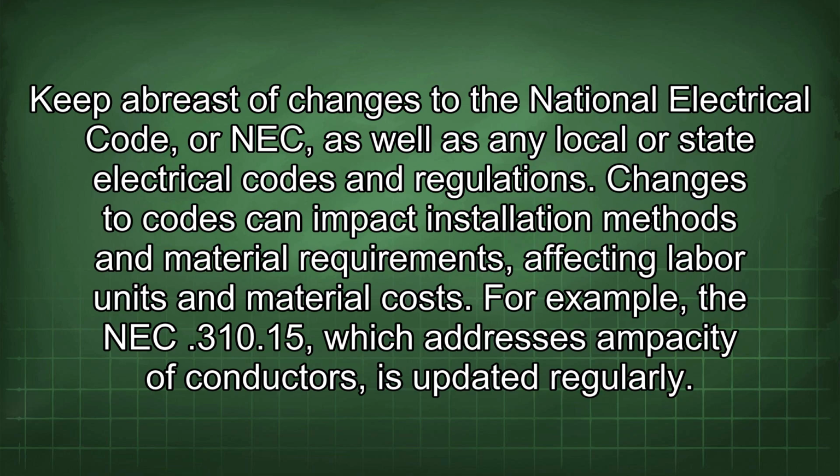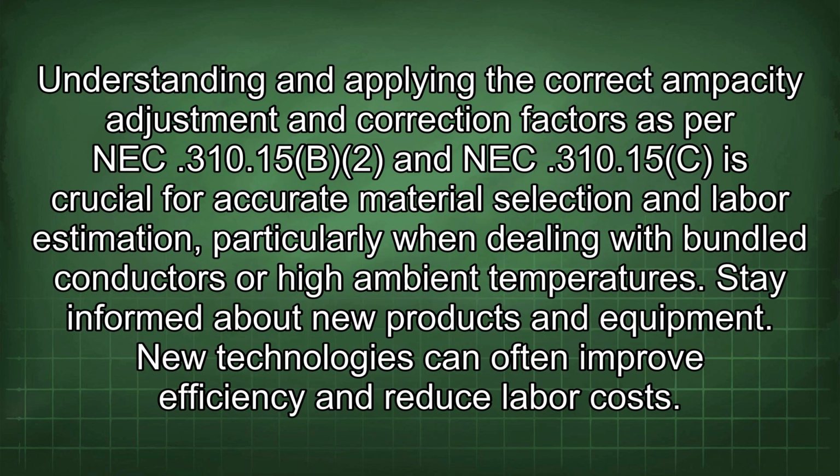For example, the NEC 310.15, which addresses the ampacity of conductors, is updated regularly. Understanding and applying the correct ampacity adjustment and correction factors as per NEC 310.15(B)(2) and NEC 310.15(C) is crucial for accurate material selection and labor estimation, particularly when dealing with bundled conductors or high ambient temperatures. Stay informed about new products and equipment.